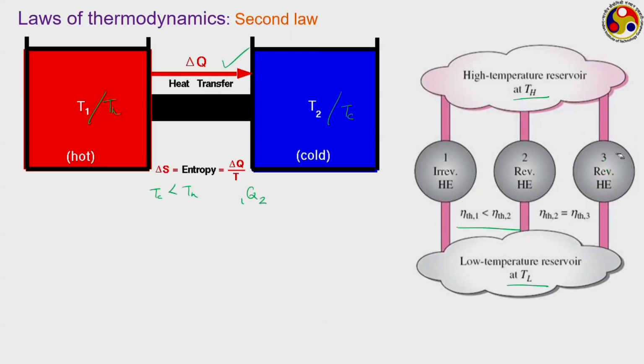So, that is the first Carnot principle, but here we are concerned about the second Carnot principle. Let us remove this one from our system. We have now 2 and 3, both are reversible heat engines and both are working between the same two reservoirs. Then the second Carnot principle says that both of them will be having the same efficiency. That is, in more formal terms, the efficiency of any Carnot engine working between two given thermal reservoirs, any reversible heat engine or Carnot engine working between two given thermal reservoirs will always be the same.